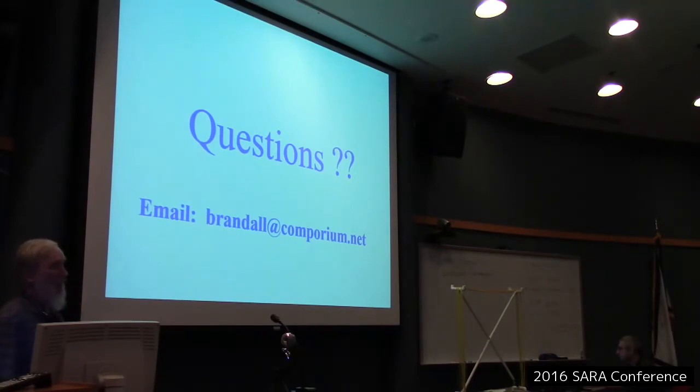And then there's another grade that begins to work about 200 megahertz and gets real good at 300, and then goes on up from there. There are cases where I've put 2 or even 3 ferrites next to each other, of 2 or 3 different flavors, to make a wide band choke. So yeah, I appreciate you bringing that up, because I have been burned by that sort of thing before.